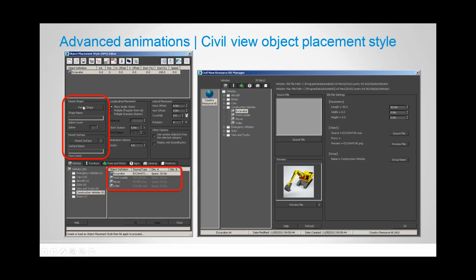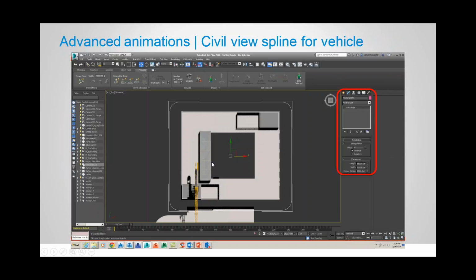And you can start to set up shapes or paths for them to follow. You can set the kilometers per hour, so there may be a limit on how fast they can go around the site. There may be a speed limit on the site as well. So you can start to simulate these with actual real-world parameters. We simply bring this information from Navisworks into Max. This is just setting up a rectangle. So I'm looking at my construction vehicles and a zone for moving around the perimeter of the building.